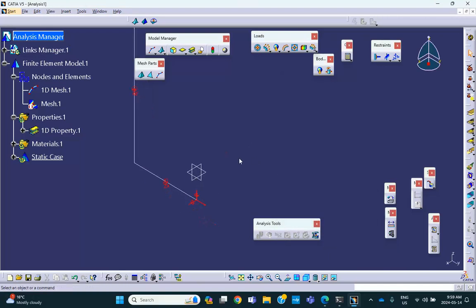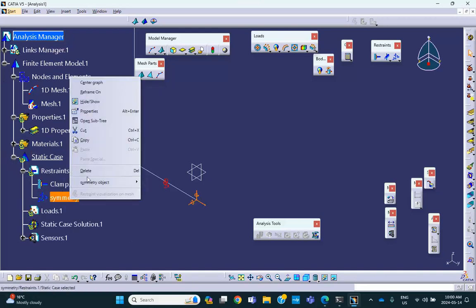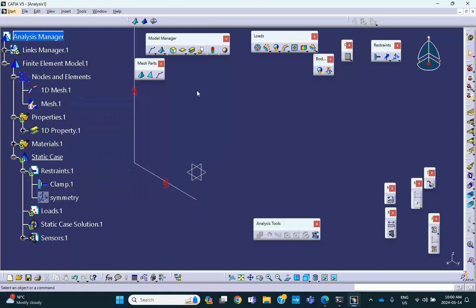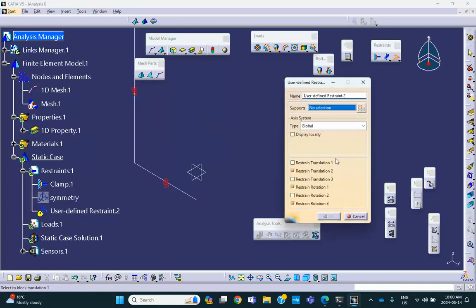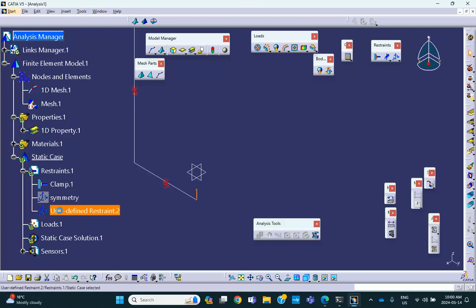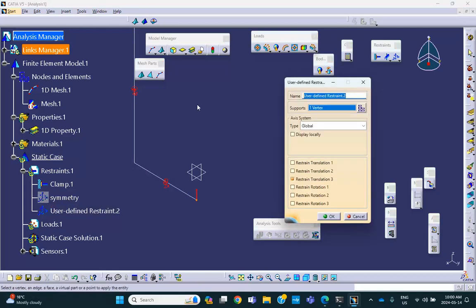Now I want to push this thing down by some amount. So let me actually hide this so that you can see it better. You get confused. So this is the restraint that I put. I'm going to hide it. Yeah, good. Now another one. I want to push this point down, right? Pushing down means that you first have to make a zero downward or upward displacement. Oh, by the way, let me also call this thing pushing down.